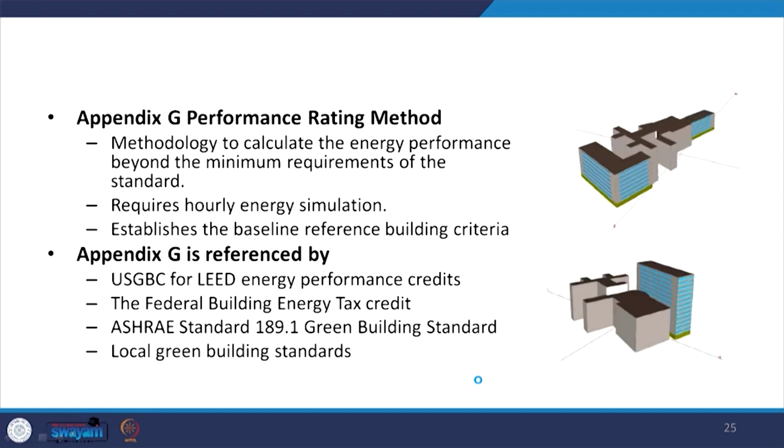Now, when we are talking about the whole building performance method, we have the Appendix G performance rating method, which largely drives the whole building simulation approach. This is a methodology to calculate the energy performance beyond the minimum requirements of the standards. It mandatorily requires an hourly energy simulation, and it helps to establish the baseline reference building criteria.